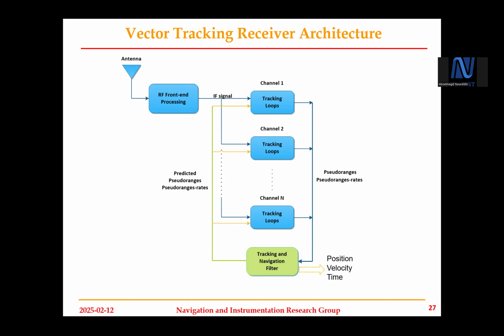Yes, we are assuming we know them, but the signal while propagating had some errors, for example, multipath. We still know the satellite position and velocity accurately, but the problem is here inside the tracking loop. That triangle, if you remember, was not balanced. It was shifted or squeezed a little bit. How can I use this position and velocity information to fix the issue with the individual channel?